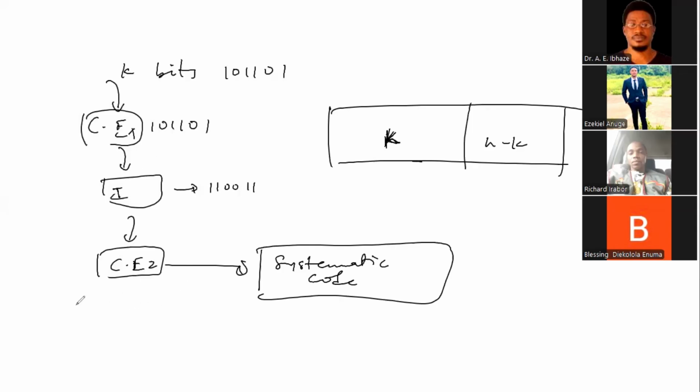And then we also now decode this. So it means that the soft input, soft output decoder will now take in this systematic code from the second convolutional encoder to estimate the original data. Okay, so the interleaved version will now be fed into a second decoder because we performed two encodings, so we're going to also perform two levels of decoding.